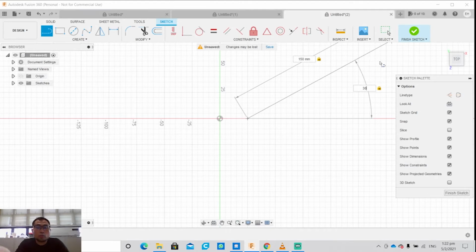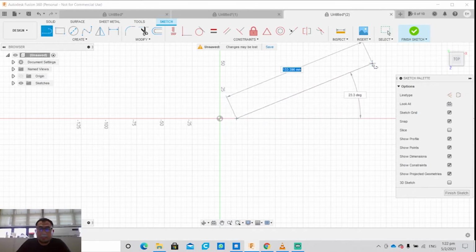All you have to do right now is click the left mouse button. Unlike that, if you want a freehand building of your sketch, you can click on a point and roughly gauge where the other point is that you want it to be placed. You have these two options: you either specify or click for a rough estimate.